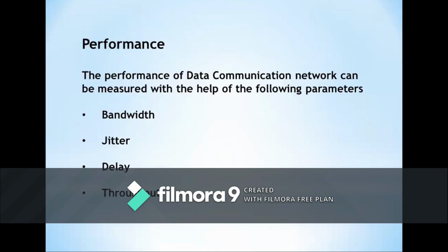The bandwidth is also important in deciding the channel capacity C of a transmission system. The channel capacity C of the transmission system is the maximum rate at which bits can be transferred reliably. The relation between C and the channel bandwidth is C is equal to B log to the base 2 of (1 plus S upon N) bits per second.